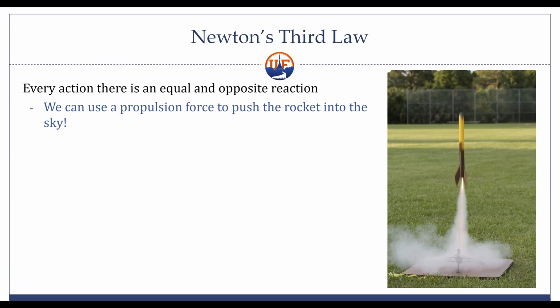Leonardo asked, is drag a major component to consider for motors? No, but it's a major component to consider for the rocket itself. The reason I didn't consider it there is because I talked about when it's on the launch pad itself. Right now, since the rocket's not moving, there's no drag on it yet. It will be, and we're going to talk about that very soon. But no, it shouldn't be a component for the motors because for the most part, the motor is going to be inside the rocket.